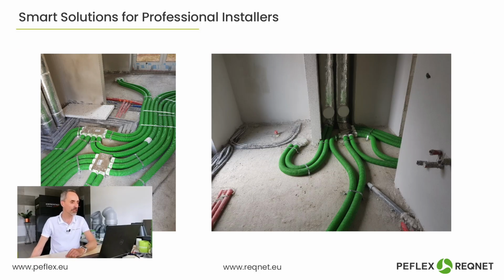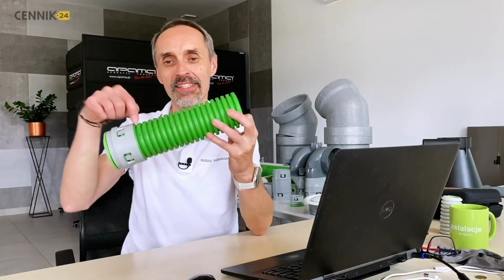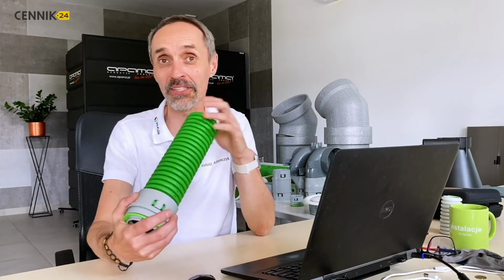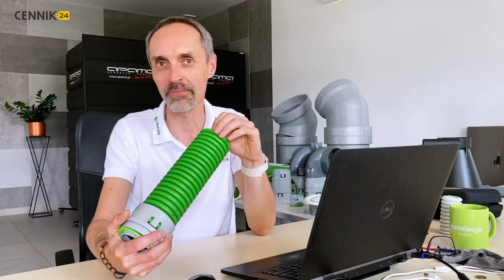The 75 system. There are fewer of these pipes now, yes, but again, they have a greater height. And here too, a good solution is to properly plan the installation so that there are no clashes with other systems, like the water installation or the electrical installation, because if the rule of first come, first served is applied, it may turn out that in those 10 centimeters of acoustic insulation, there won't be enough height. And I've seen photos where, for example, the top of the pipe was already sticking out of the insulation, or, for instance, out of the poured concrete, right? Or out of the flooring.